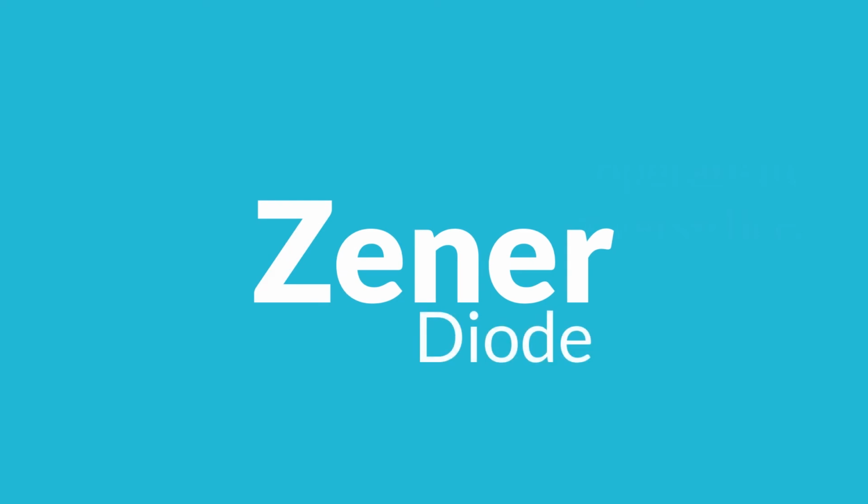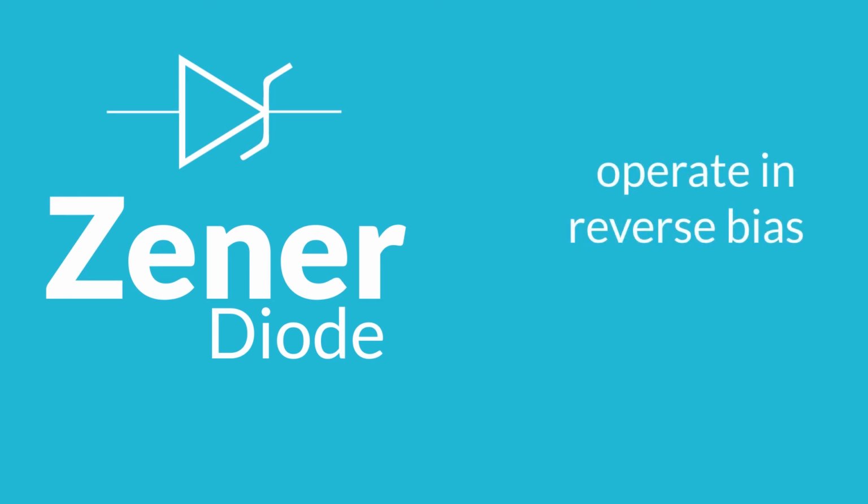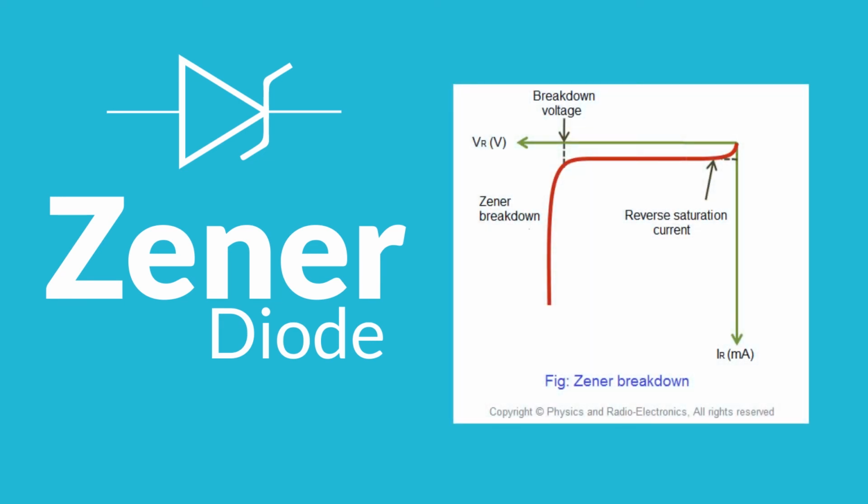Zener diode. A Zener diode is a diode which is specially designed to be operated at the Zener breakdown voltage under reverse bias. This diode is heavily doped to get a narrow depletion region, giving a strong electric field inside. When reverse bias voltage is applied to a Zener diode, it allows only a small amount of leakage current until the voltage reaches the Zener voltage. When the voltage reaches the Zener breakdown voltage, the current increases rapidly.